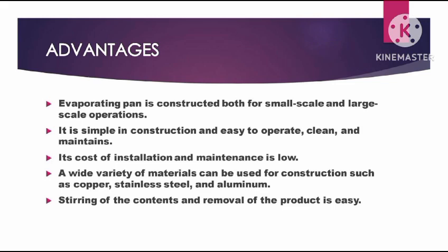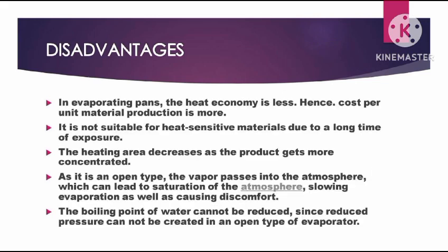It is easy to install and the cost of maintenance is low. For the construction of the evaporating pans, a wide range of materials can be used, including copper, stainless steel, and aluminium. The contents of the pan can be stirred and products can be removed quite easily.